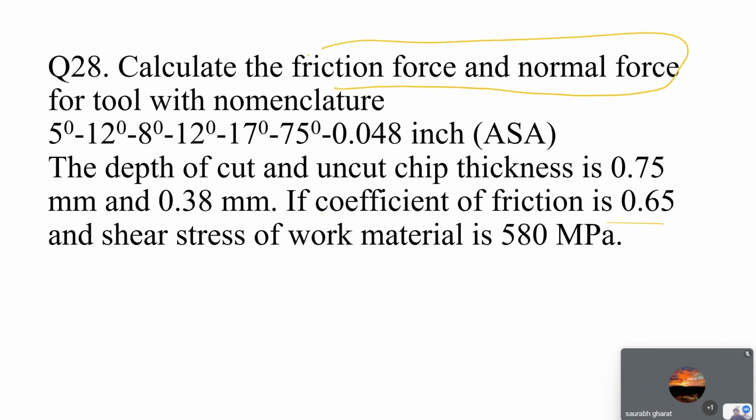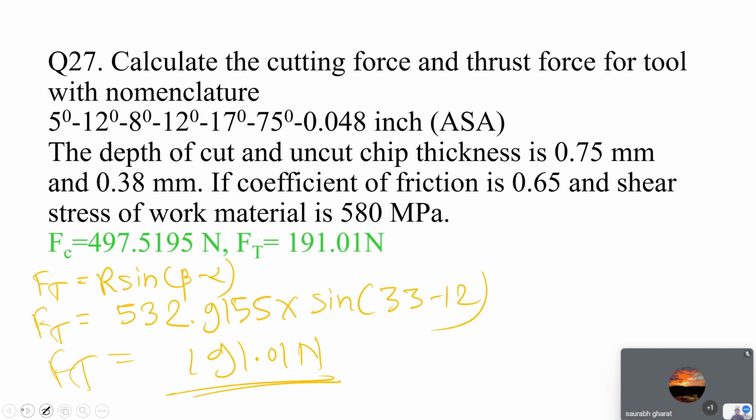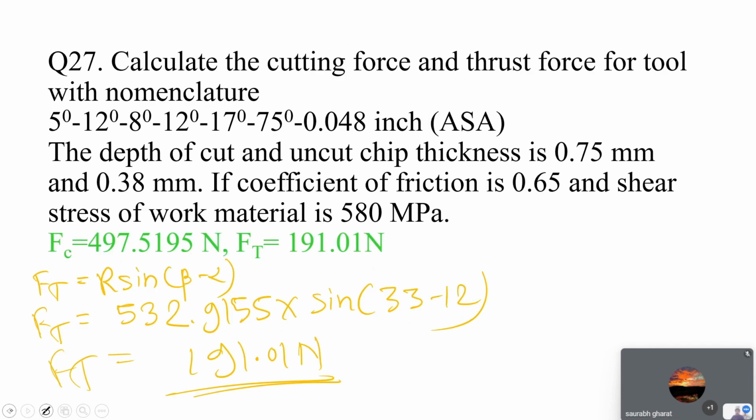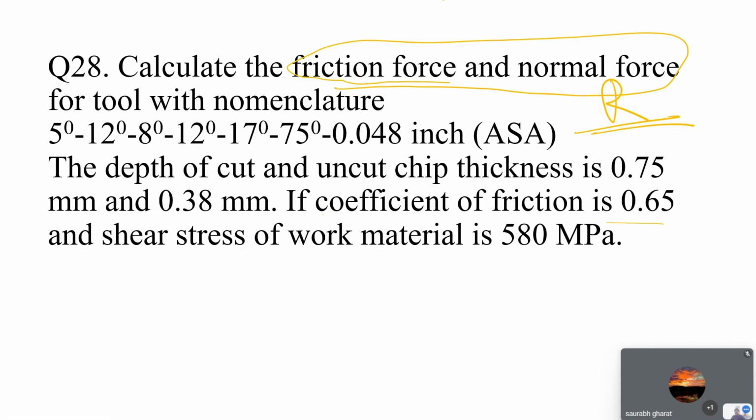You already have R, so it is easy to calculate, because the problem is exactly the same. Just need to calculate the friction force and normal force. It was cutting force and thrust force earlier; here it is friction force and normal force, which you can calculate easily from R.